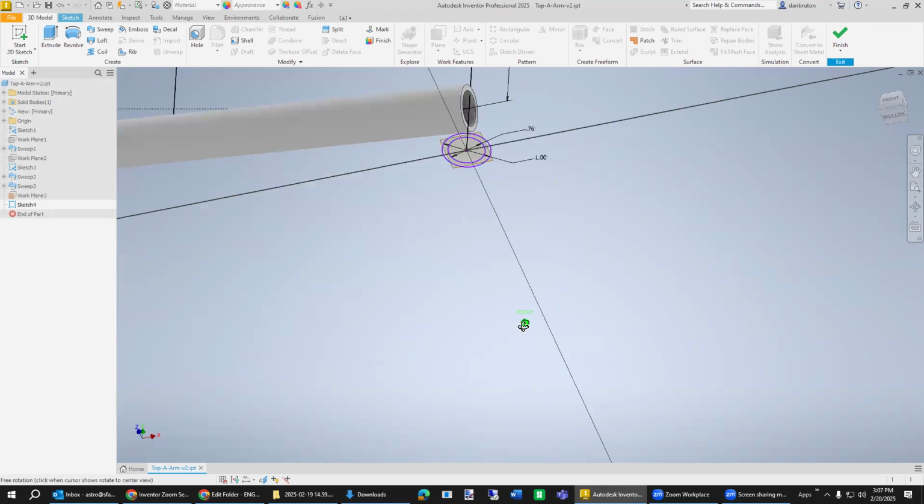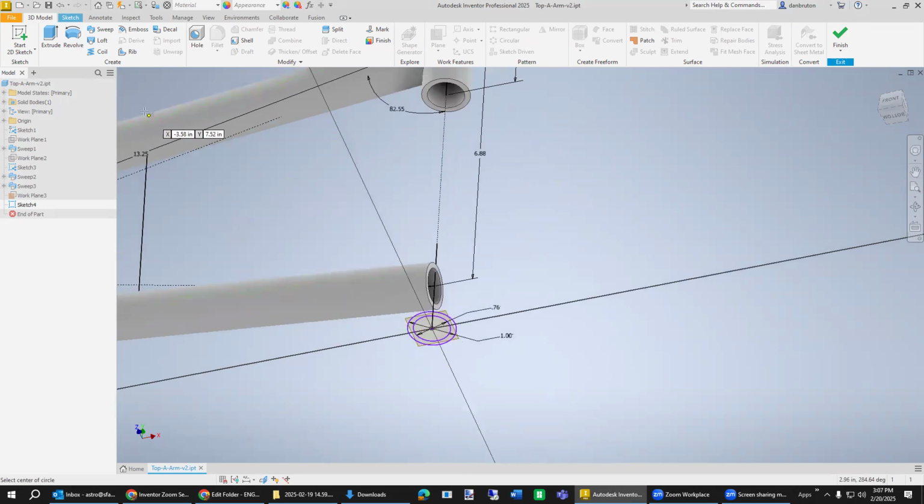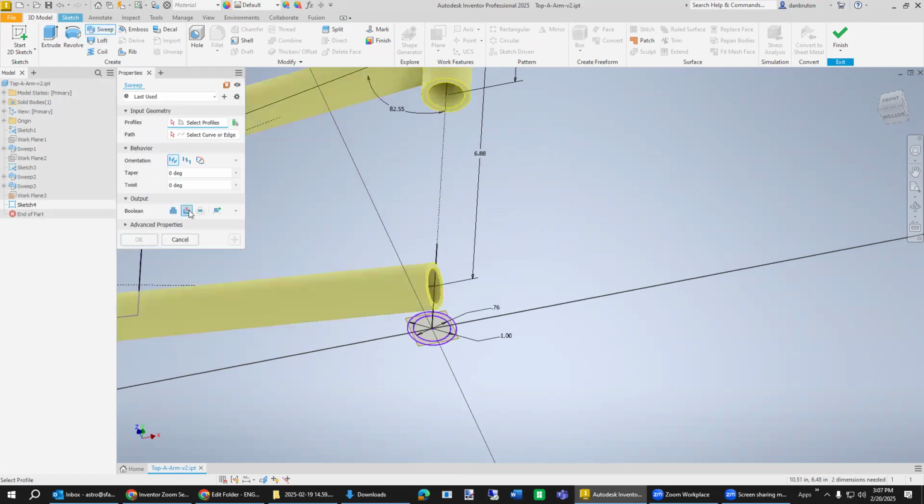virtually with Autodesk Inventor. But then, you'd also do that with a milling machine as well with your tube in the machine shop. So let's perform a sweep cut, this one, and we want to select the profile, which is the outermost one, which will basically knock everything out along the path that we select. We want to make sure it looks right. Usually it's going to be red if it's going to subtract it. We don't want to finish just yet.